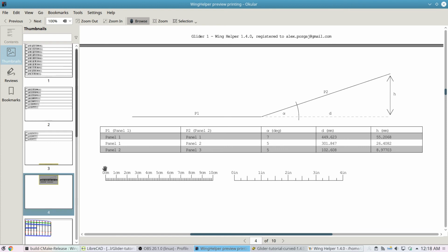And this here is also actually very important. I usually print this page first and then measure on the paper whether this line here is actually 10 centimeter long. If it is not, then this usually means that something is wrong with the printer setup. Most probably the margins are not set to 0 millimeter. So my recommendation would be print into the PDF file, then print this side. If the printer puts out this line as 10 centimeter or 4 inch on this side, of course, then you are ready for printing.